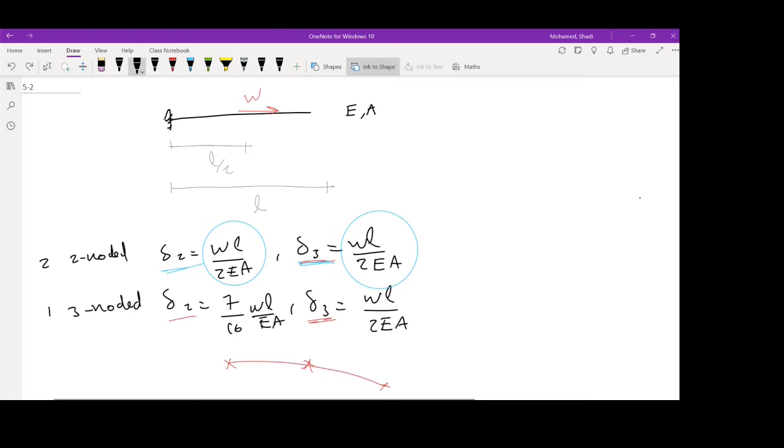So you have the cantilever fixed at this point, and think about the stress starting from this free end, and you are moving inward, right? This part has no stress in there at all. This part is still free from stress. As you are moving in this direction, the stress is zero in this part of these elements up to this point, right at the middle.